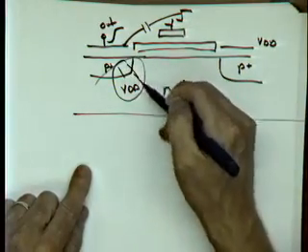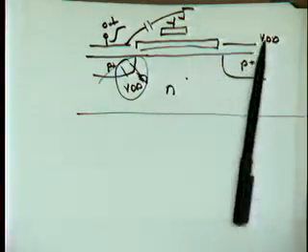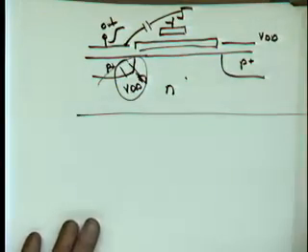And I start injecting current directly from my drain into the substrate. And this can have some nasty effects. I mentioned this, I think, last lecture or 2 lectures ago, something which is called latch up. I'm throwing charge around in the substrate. We don't like that very much because there's some weird devices hitting in here.